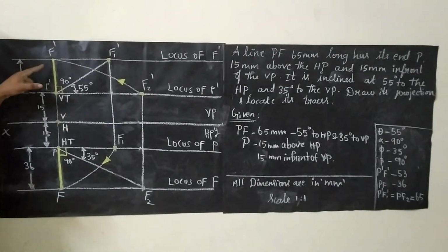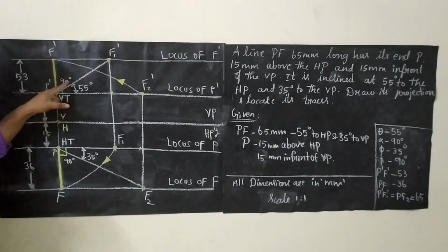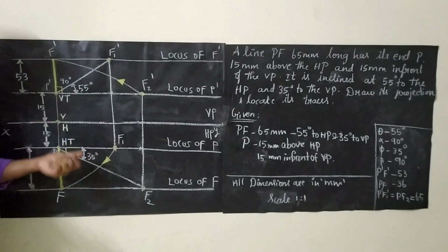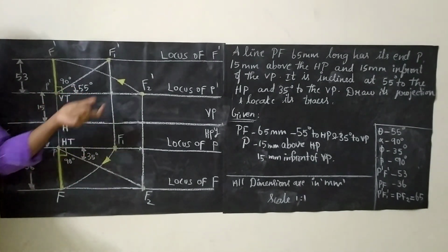See to it that since we are having the locus line itself, I haven't taken an extension line. But generally the extension line should be perpendicular to whatever line you are drawing, and dimensioning line should be drawn with your H pencil, and see to it that the number should be vertical, written with your HB pencil. The angle of the front view, that is alpha, we will be having 90 degree, beta is also 90 degree, theta will be 55 degree, and phi will be 35 degree. So these two angles are the angle of inclination for the true length as given in the question.